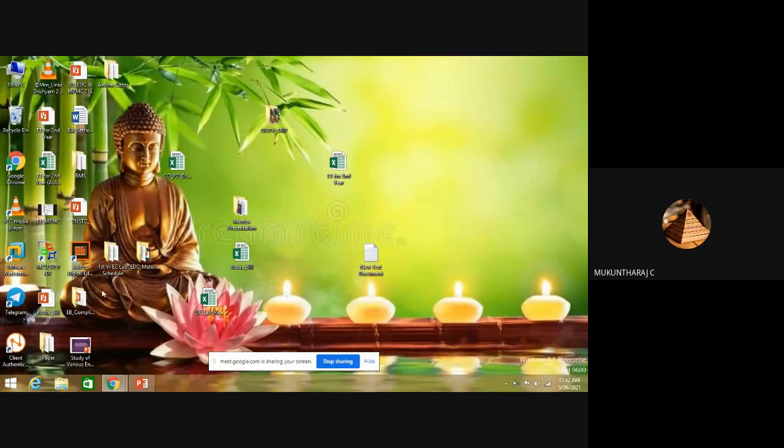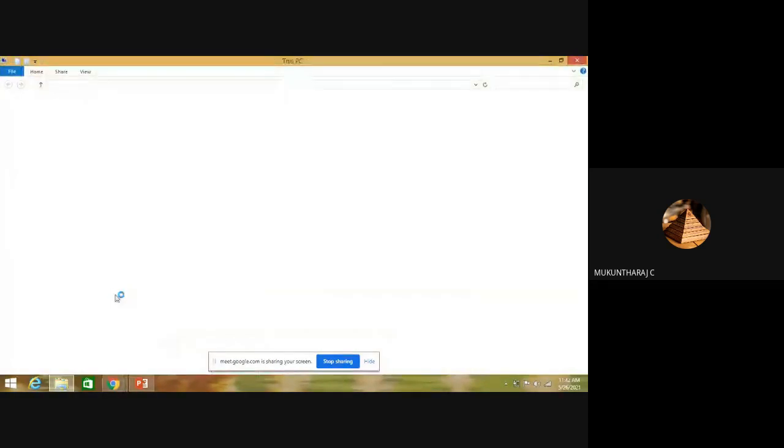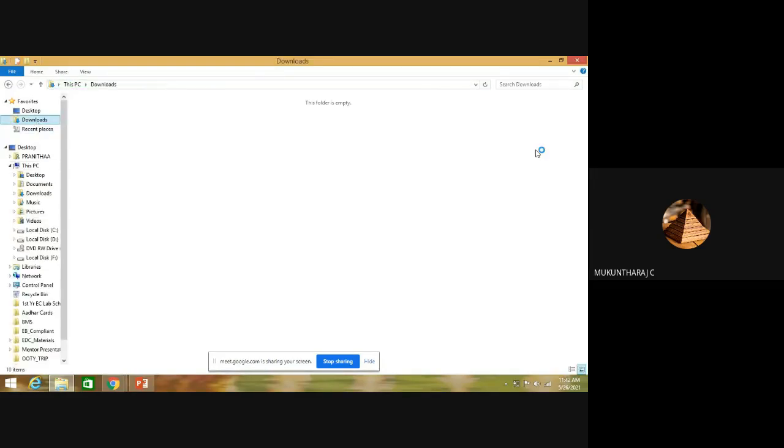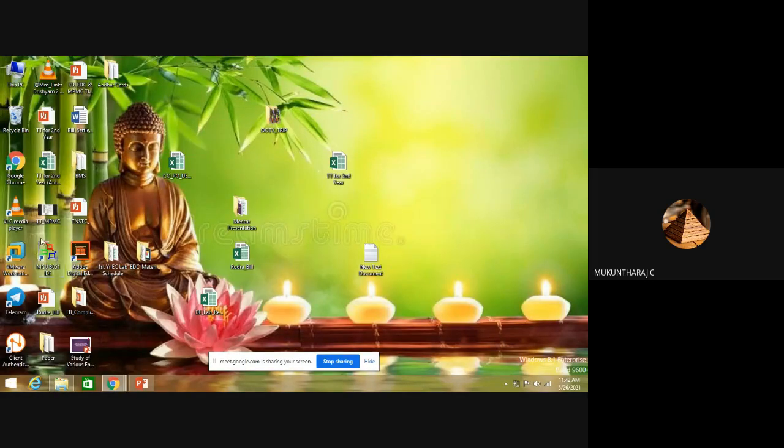The very first step is to install the SDCC compiler first. You can check my download folder; I have downloaded and installed the SDCC software. Sir, shall I continue? Yes, continue. Thank you. So after installing SDCC, you can install MCU8051 IDE. That SDCC will be configured to this MCU8051 IDE. Once these two software are installed, you can open the MCU8051 IDE.